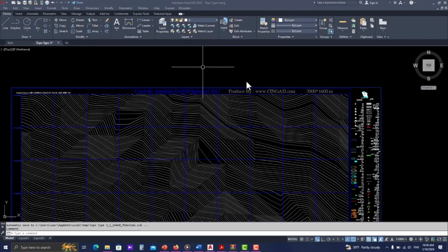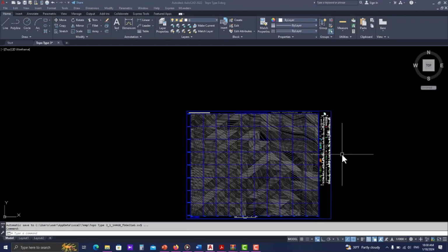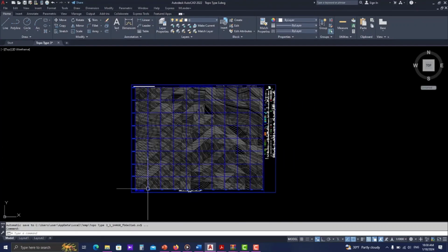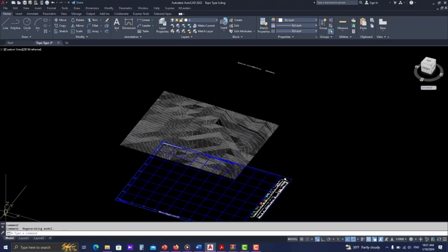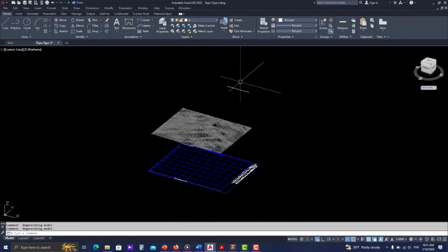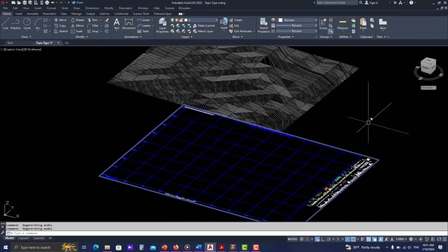So probably everything has been moved along that direction, and right now, for solving this problem and working with only two directions, which are X and Y, I have imported a plan from topography, and I just made this example to show you that as topography is not flat, it would bring us these problems. Here, if I hold down the shift button and then navigate, check it out, you'll see we got X, Y, Z directions, and as you can see the topography, the plan and the text are not aligned.